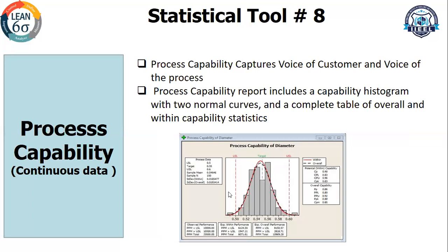Once you give this data, you get the statistics on the left side. You get the CP, CPK on the right side, which is an indirect measurement of the sigma level, the quality of the data. The DPMO, defects per million opportunities, is what is measured here, which is equivalent to some Six Sigma level. And the CPK should be 1.33 if you have a world-class process. So it's 0.83 here. So you need to reduce variation. You have some defects, so that process is not capable.